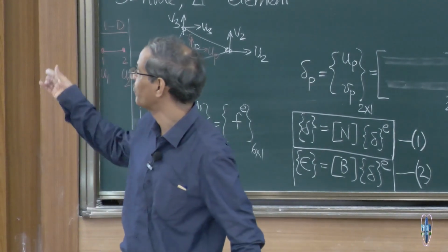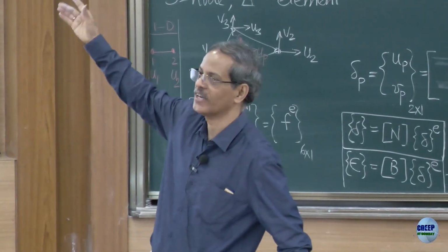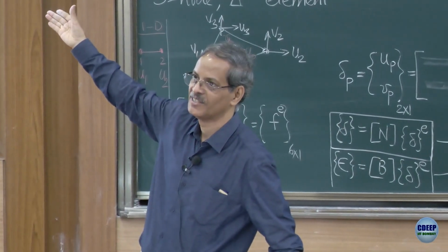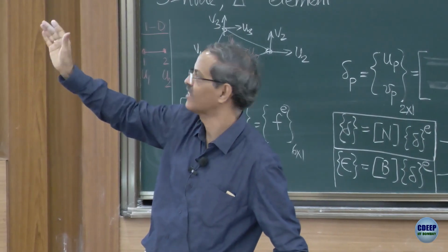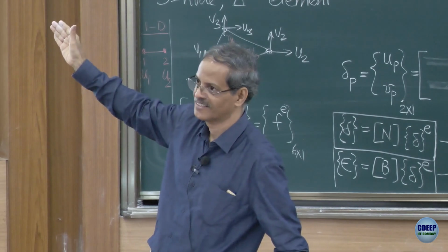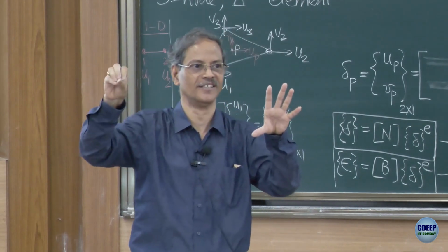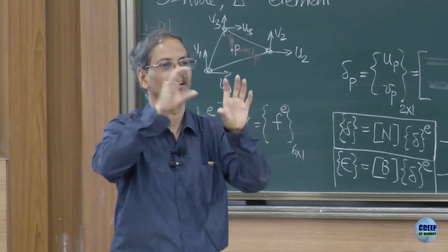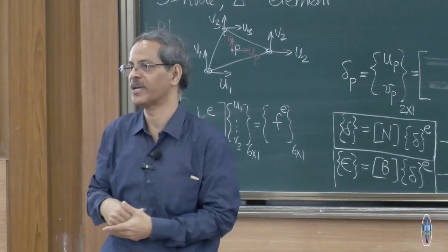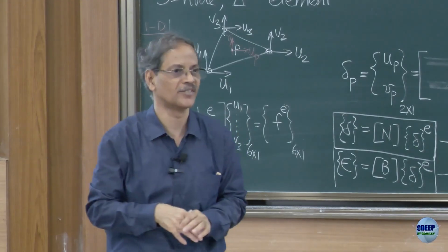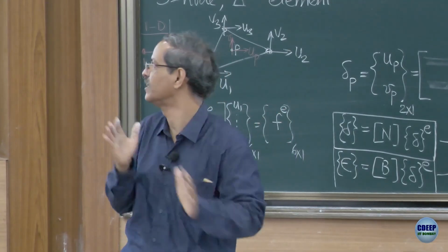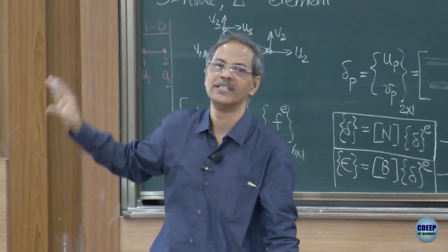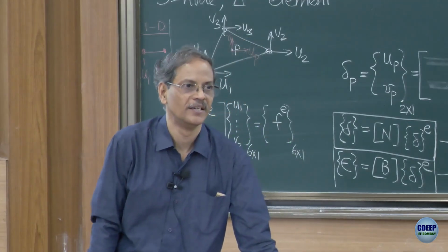Why is one delta coming? It is like half K x squared. K is the in-between term, the stiffness, x into x, delta transpose delta. So it will be half K x squared, its derivative with respect to x, x squared will be 2x. So half and 2 go, you will get K into x. That is how you can easily visualize the process.